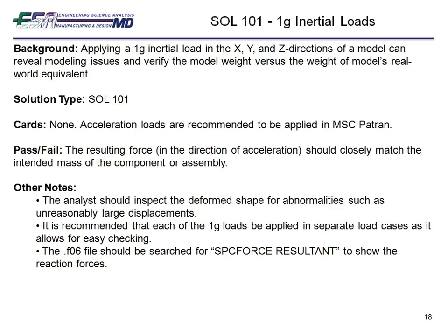And it is recommended that you apply each of the 1G loads in separate load cases so that you can easily verify that the resulting weight of the model is in the direction of the inertial load. And the F06 file can easily be searched for the output force by searching for MPC force resultant, which shows the reaction forces of the model.